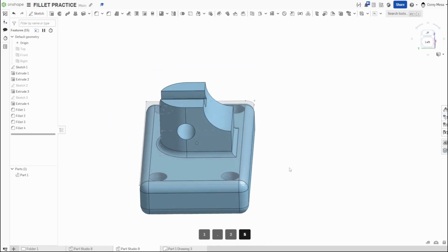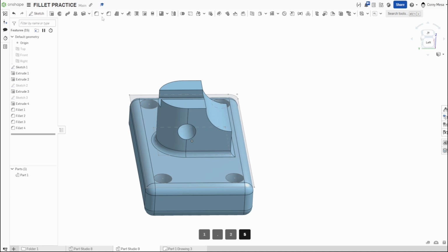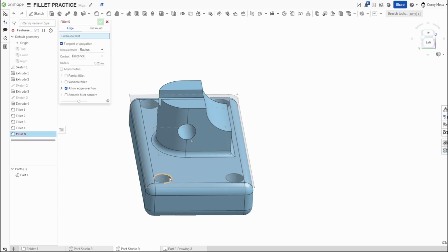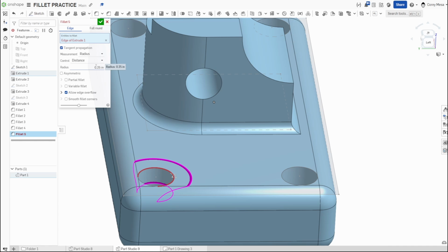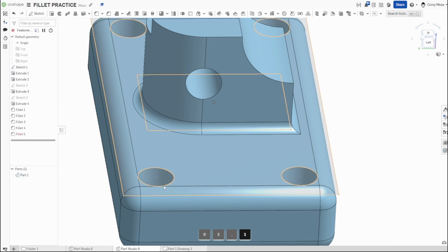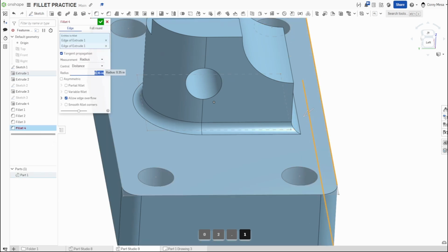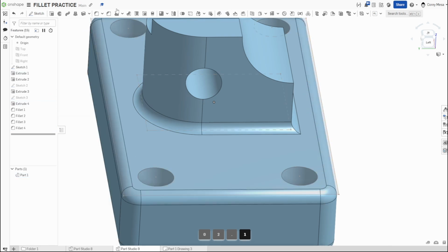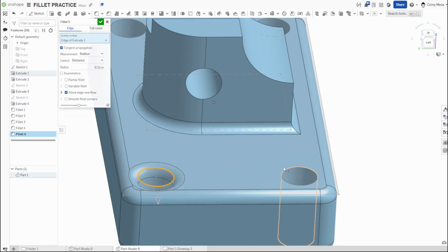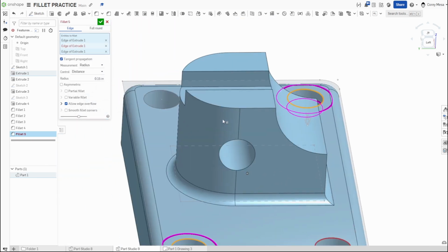Another way to do this too, you could use this to show kind of like a countersink almost, or just rounding holes. If you're using this for printing and you want to make sure the bolt holes can line up pretty easy, you can do it on your holes. So we'll go through here and slide that back. A little more, 0.02. Oh, we made it too big on our other one. Let's go back to our fillet. Oh, there we go. And we'll round this corner. So if I click my holes, you can make them kind of look like grommets.